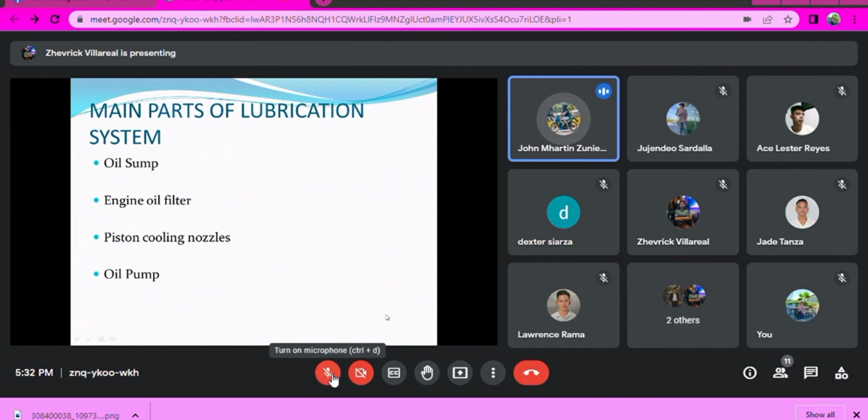The next is the piston cooling nozzle. Continued usage of low quality gasoline can lead to a cracked piston. A fractured piston might also be the result of the exhaust gas recirculation system failing. Cheap tuning, lack of piston cooling, and a faulty injection nozzle are other possible causes for a cracked piston.